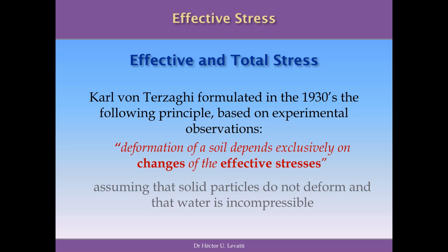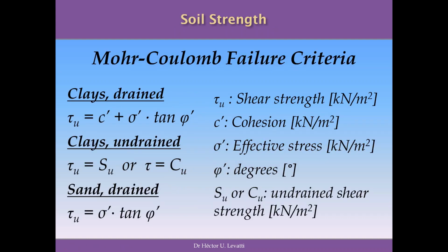So what matters in a geotechnical problem is that you have to work with effective stress, because effective stress is what changes everything in soil problems or geotechnical problems. And this definition or this concept is limited, because it assumes that the solid particles are not deformable and that the water is incompressible. So this has mathematical implications that we are not going to study in this video, but we can study in videos in the future.